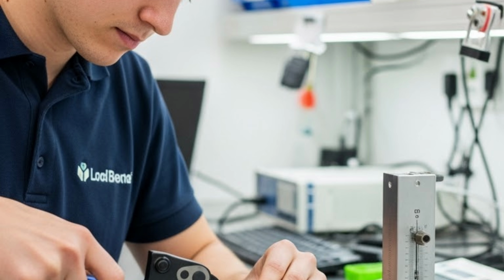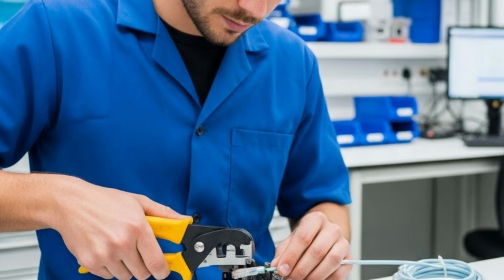Test samples preparation. For this test, 3 cable samples are taken. Each sample length should be at least 5 times the cable diameter, with a minimum length of 150 millimeters. Any covering outside the test component must be removed.